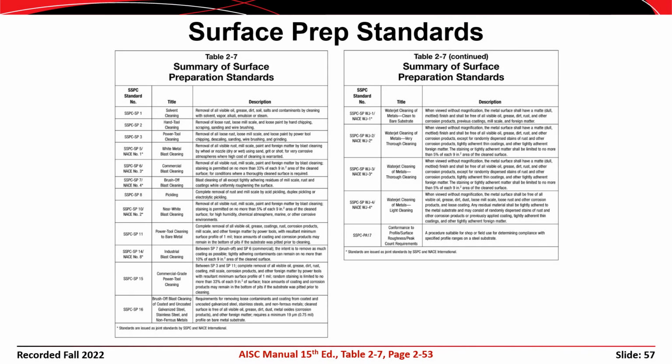So the last couple of tables in Chapter 2 deal with surface preparation standards, and that's a bit of a right turn for this particular lecture, but it's worth mentioning, and this is as good a place as any, I suppose. SSPC stands for what? The Society for Protective Coatings. And they have SP1, SP2, SP3, etc., which stand for Surface Preparation Level 1, Surface Preparation Level 2, Surface Preparation